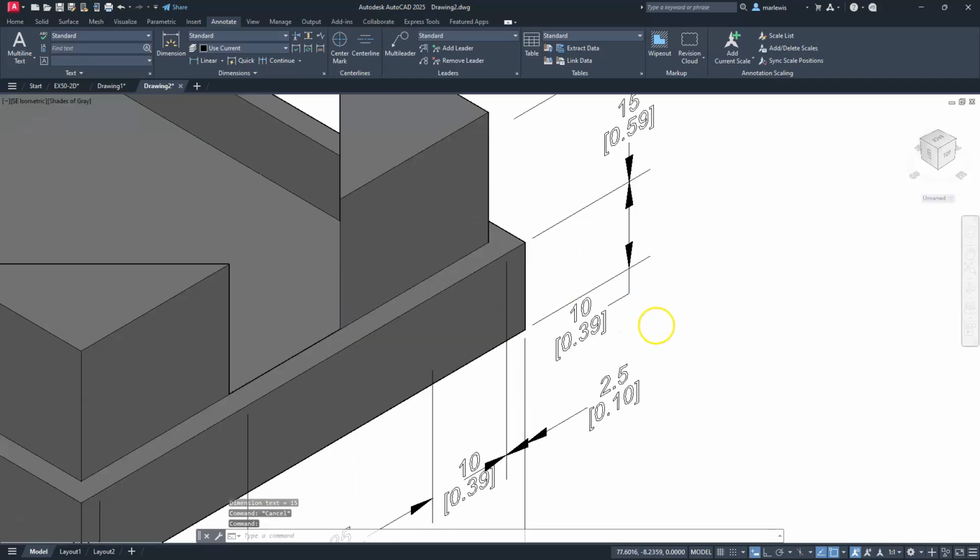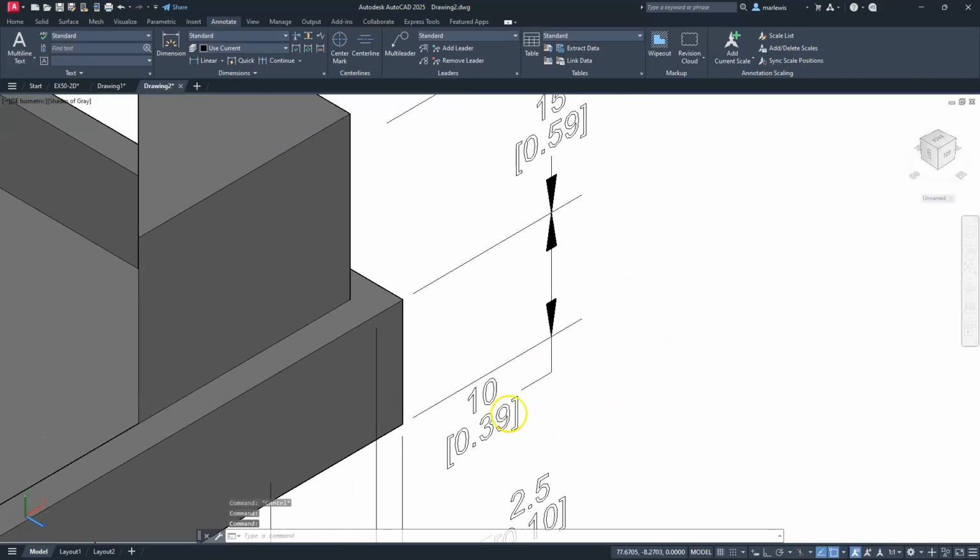And once again, we can move this if this is something that you would like to do. Remember that we can select it here, hover on the grip. Once it gives you the options, choose to move with a leader, and then just flip it to the other side.